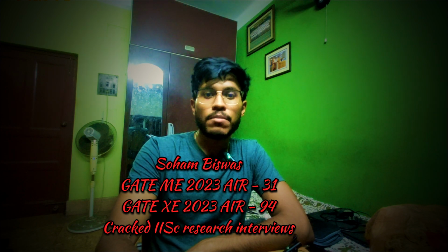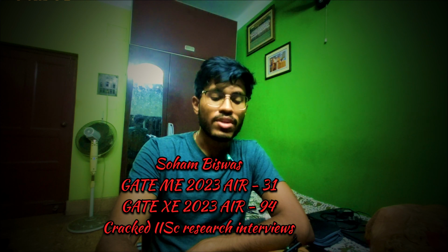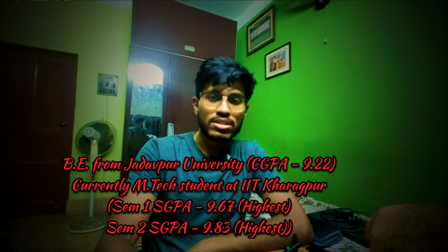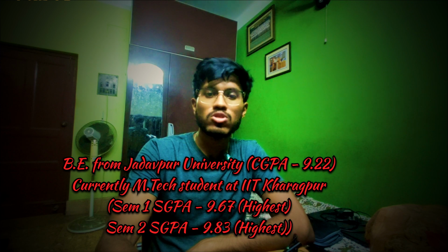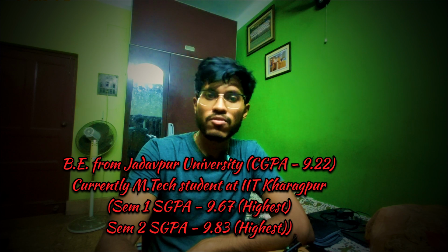and we were discussing the basics of tensor algebra as well as the basic rules of dealing with indicial notations, right? I almost completed all the rules of indicial notations, and therefore today, with the help of them, I will be deriving the fact that for an isotropic material only, the thermal conductivity tensor boils down to a constant multiplied by an identity matrix. Okay, so let us directly dive into that.